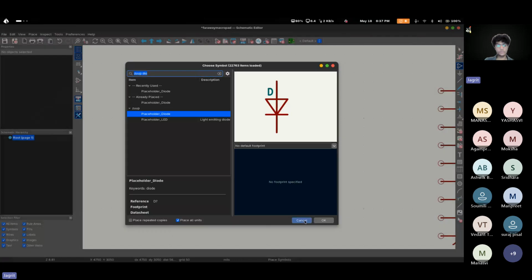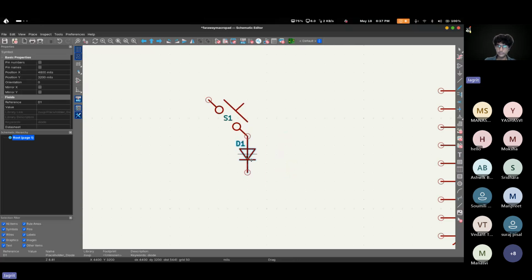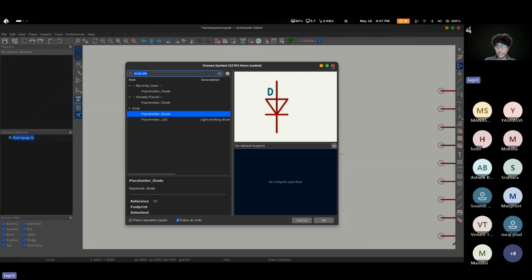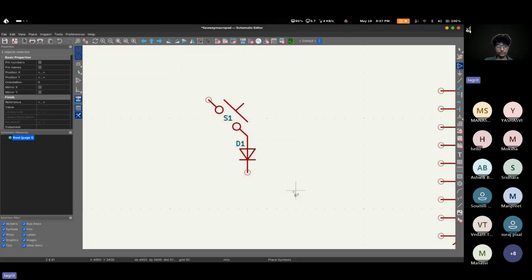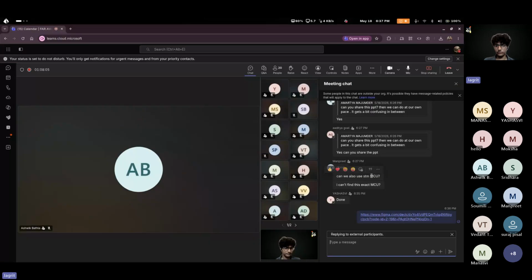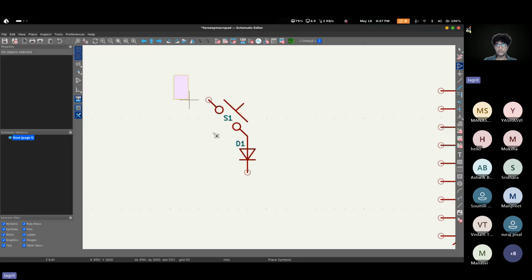What we are using at mass scale, you cannot particularly use the push button and a micromet. You will use the mechanical switches, the MX switches that we call. So when you click on diode, you need to connect it up here. This is the schematic version of a mechanical switch which is available out in the market. I think there are no doubts. When you are done up here, this is a particular switch with a diode made.